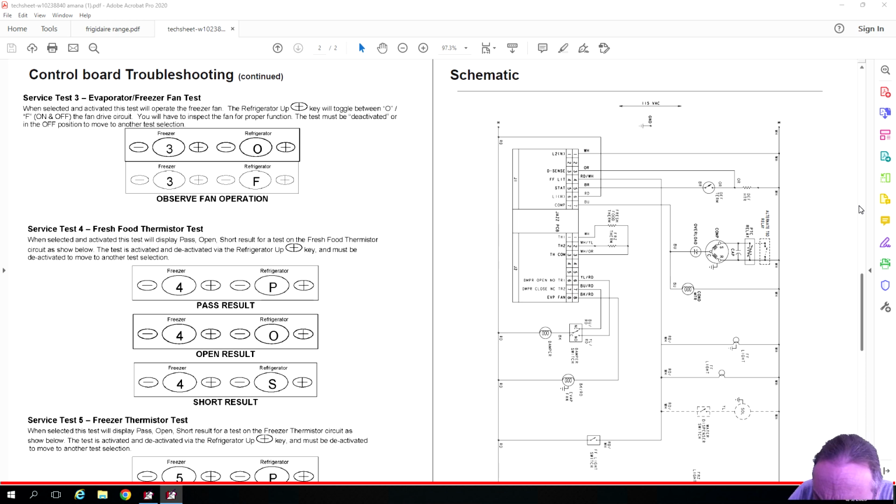1, 2, 3, 4. That's pin 4 right there. So now they're not staying tight because I don't have the right connectors on here. But pin 1 and 4, let's see if it lights up. So, why did that happen? If you look, it came on, came off. So it's working on 1 and 4 and not 1 and 6.